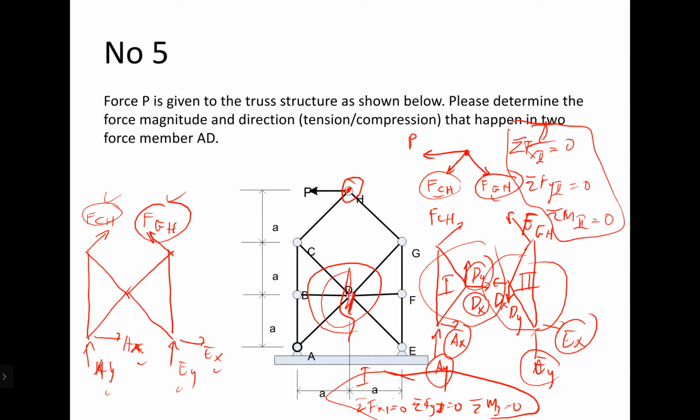Okay, I'll do the same. Oh, you use the joint method. If you use the joint method, then you will be able to solve this. Then after that, I look for zero force members: TE is zero, TF is zero, right? Yeah, like that. After you solve this and this, then you try to solve point D, right? Yeah, correct. Okay, can you solve it?